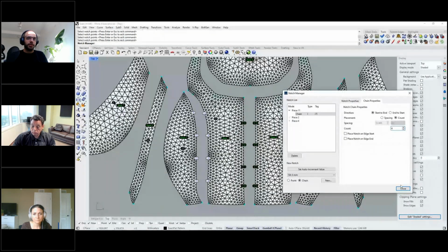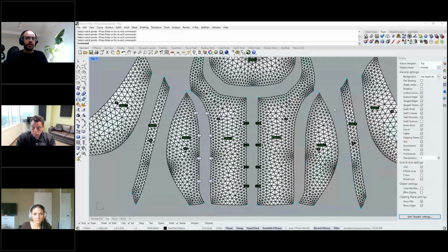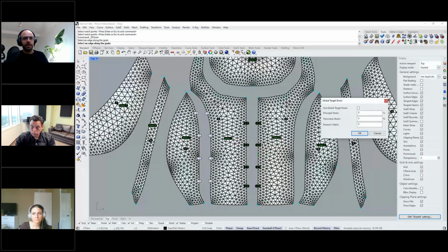So then we can take a look at our grain line tool. For example, if you are working with a woven material that has a specific grain orientation, you can use the grain line tool to mark that orientation on the pattern piece. This will create a straight line that will go to a specific layer with a specific layer name and color in the final DXF file that we create when we send this to a cutting machine. This way, if your cutting machine has a nesting engine, it will be able to pick up this grain line and use it as a reference to rotate the pieces automatically so that the grain lines become adjacent to the x-axis of the cutter and so that your pieces become aligned with the grain of your fabric.